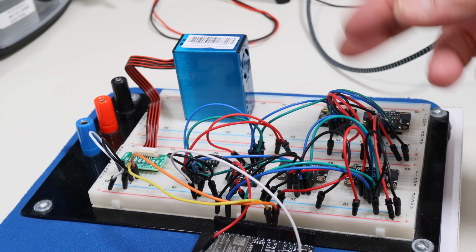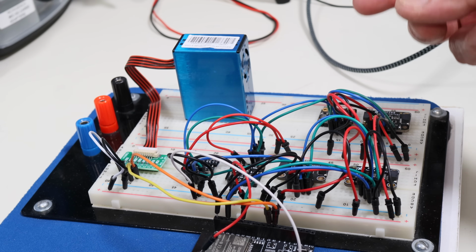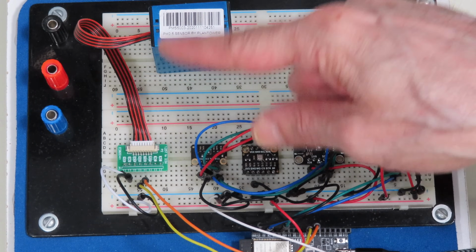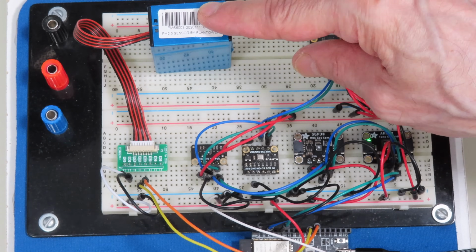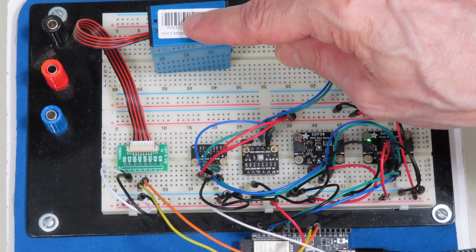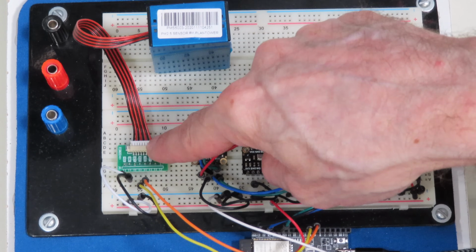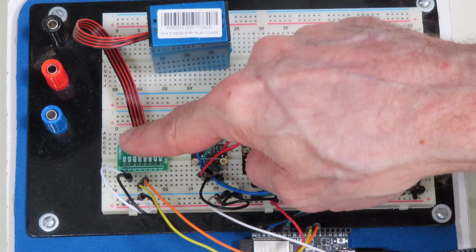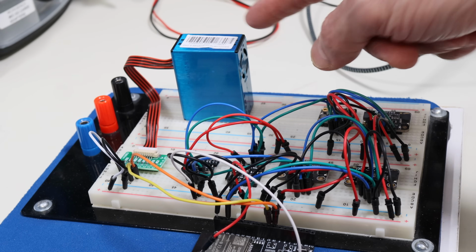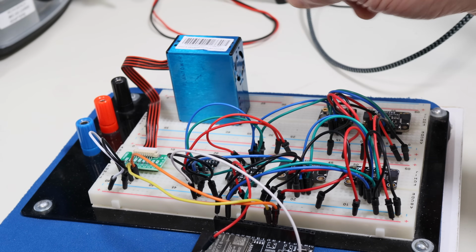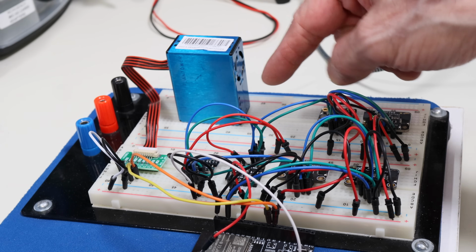You can also get these from people like SparkFun and Pimoroni, and the only real difference in the distribution is the cable that they give you to connect to the box chips so that you can get at the serial connections as well as the power connections. Adafruit's cable comes with a little adapter that works very nicely on a solderless breadboard. And I've just got that wired up to 5 volts because although this is a 3.3 volt friendly device, it requires 5 volts for the fan and the laser.